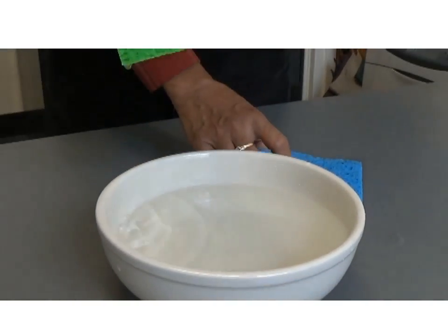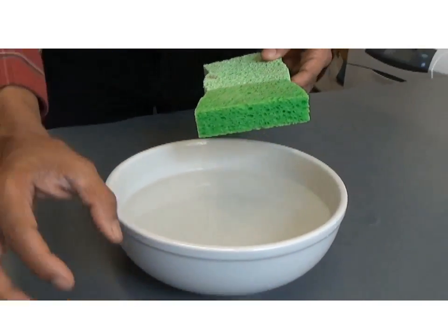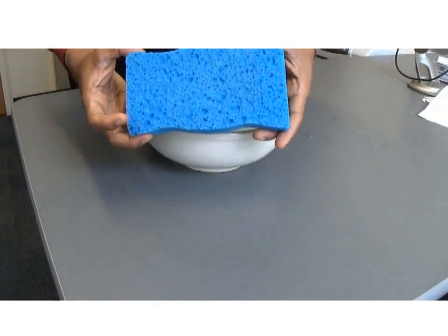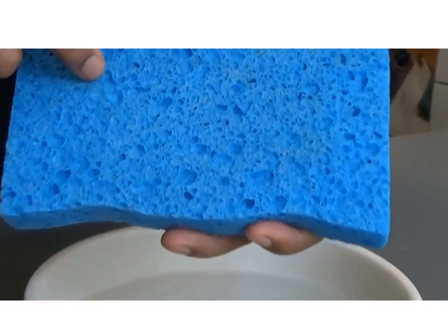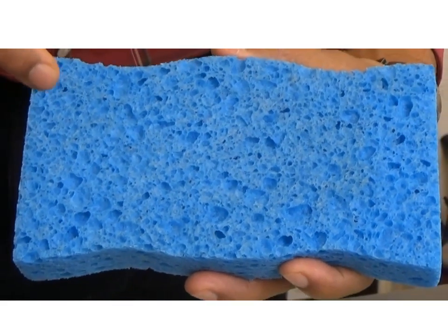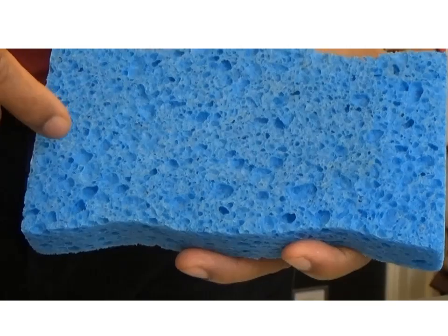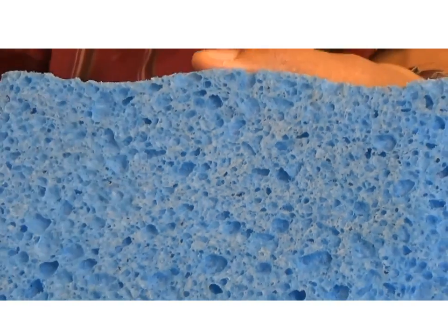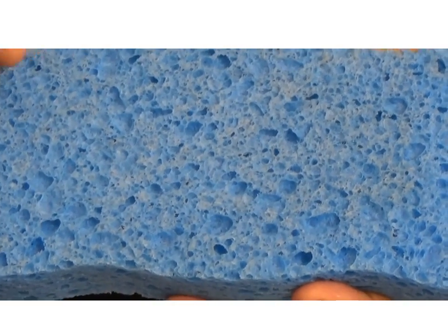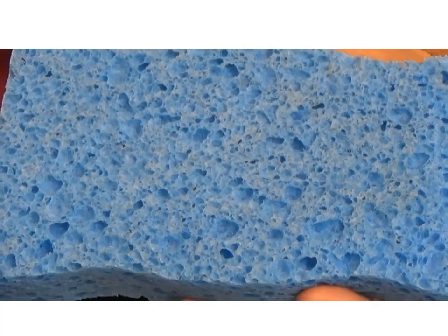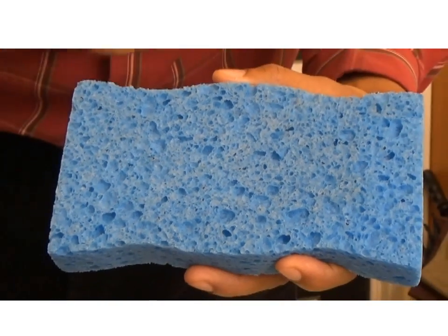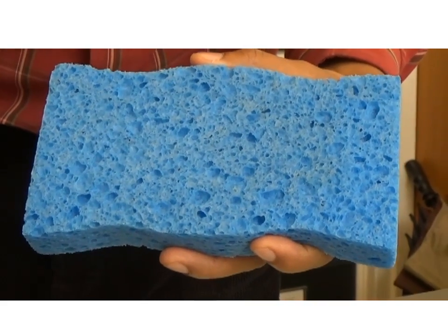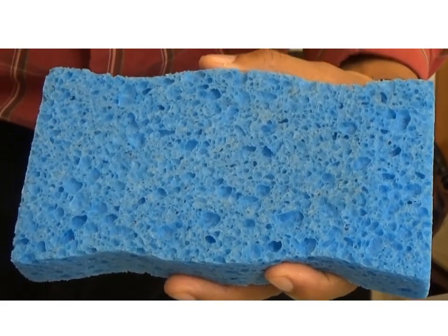And finally, I just want you to see that here is a sponge, and then you can see, for example, all the different shapes and sizes of pores. So if you want to, for example, use your laws of fluid mechanics that say how much would flow through each pore of a different size, you can do that, but you can see how it will be hopeless because there are so many pores, that's one, different sizes, and then they're tortuous of different nature. They're not going to be straight pores going from top to the bottom. So size, how many of them, and the tortuosity, they're all different.